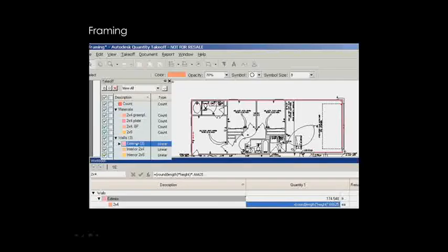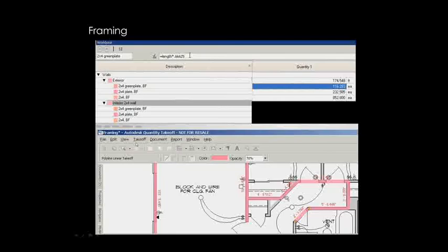Once you have the preset categories, you can start drawing your line work, you can start drawing your areas, and it's going to do a digital takeoff, but because it wasn't a model, you're manually drawing it. But it's 10 times better than drafting it by hand and having a calculator give you the linear footage and the total perimeter in the area. And because it's being tracked, you're going to easily be able to see it, turn it off, and control it from a palette as easy as you saw for the BIM model as well. And you can combine, so you don't have to go one route or the other. You can do both. So let's say an example of exterior siding.